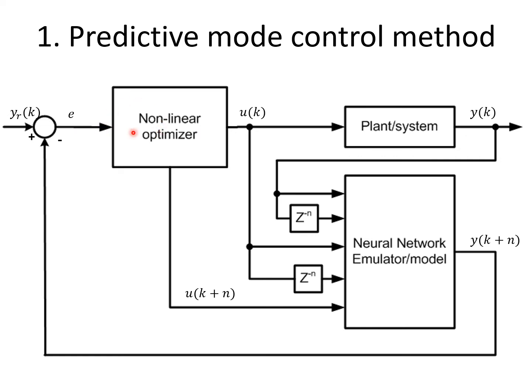This is one way of implementing neural network inside the control strategy. You don't really need the inverse model because you're basically using a forward model. The controller is done using an optimizer itself. But if you need an optimizer to use the neural network model, you can use the neural network within the optimizer. If not, you can use the first principle model, depending on how you plan the strategy.